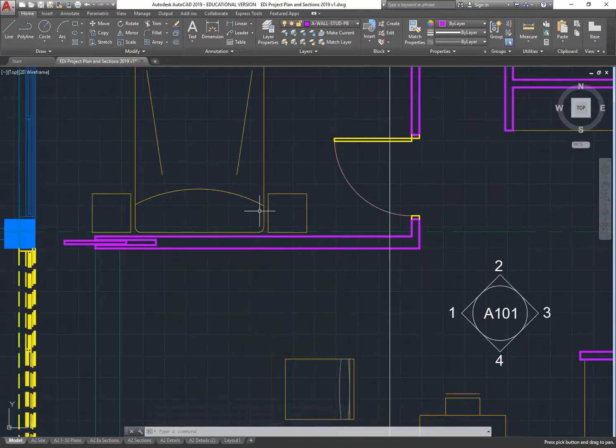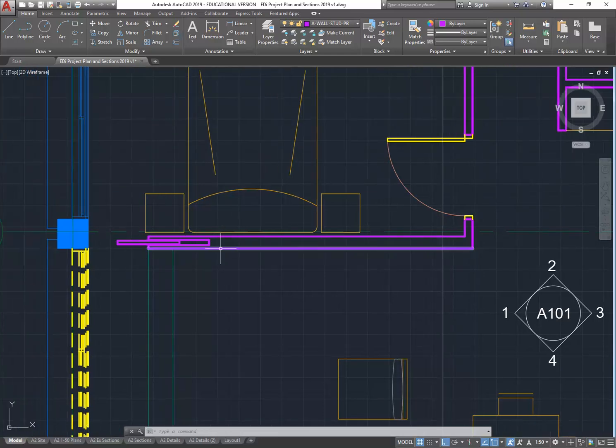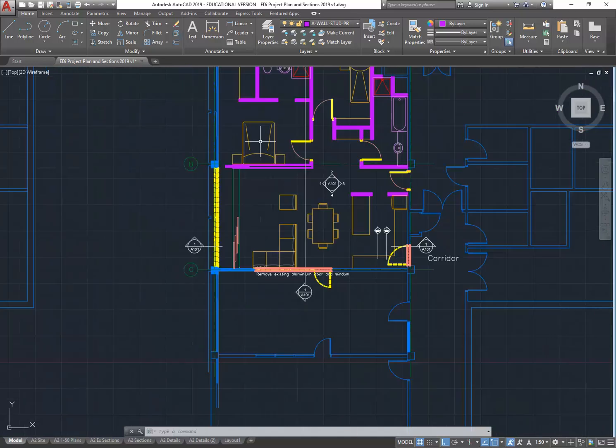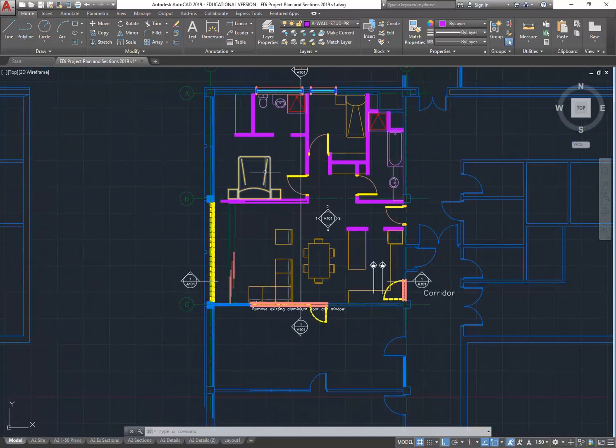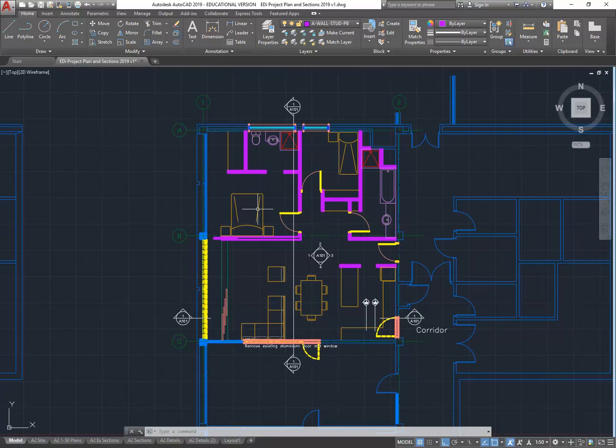Okay, that's right. So I've taken my section off this wall, and that is the one that's got the sliding door panel in it. That's why I've made it extra thick. So you'd have to have offset studs for that, and that would be a really beneficial thing as well, because it gives you more sound insulation between the living space and the bedroom.